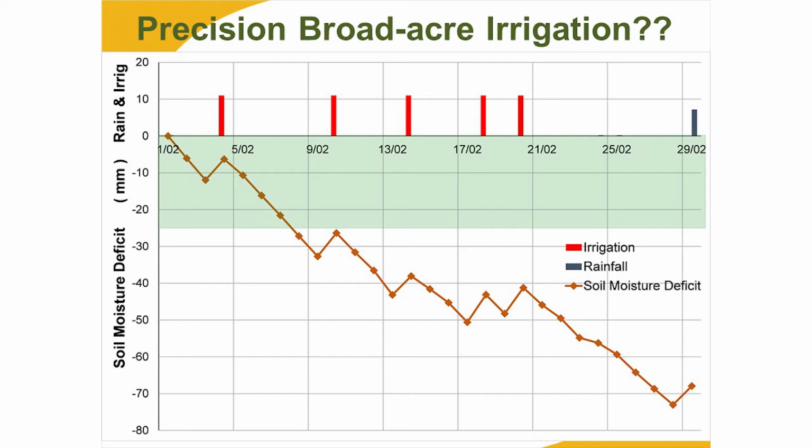And so here's a case that James has talked about a number of occasions. We developed for a South Australian field day a few years ago, where we've actually got a scenario with the water balance on a field. We've actually got the irrigation events occurring on those little red bars. And the soil water balance in the profile, we're trying to keep in the green zone, which is about a 0 to 30 millimetre deficit.